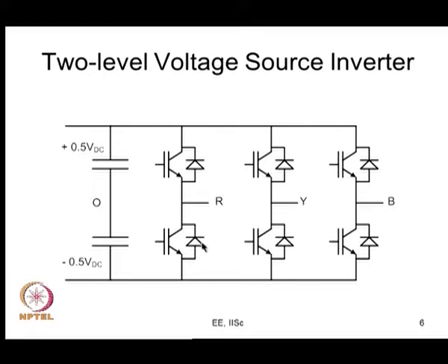So, this is a voltage source inverter. These are complementary devices, but their actual signals are not really complementary. Their rising edges are all delayed by dead time Td. After your PWM produces the signals for top and bottom devices, there is a dead time circuit which introduces this delay. So, you have this fed here now.